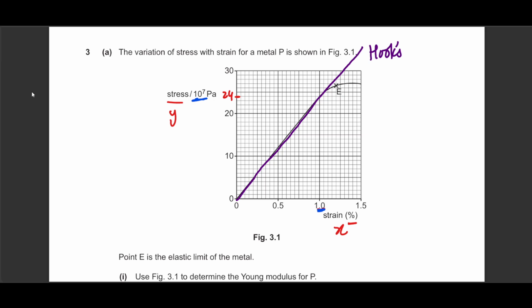Hooke's law is a proportionality of force and extension, so the moment it deviates away from that path is the point where we find the limit of proportionality, because in this region it is definitely following Hooke's law, being proportional, a straight line mathematically. The moment it starts deviating away from it is the point where it starts disobeying Hooke's law. So this will be the coordinate which is going to be pointed as Q.